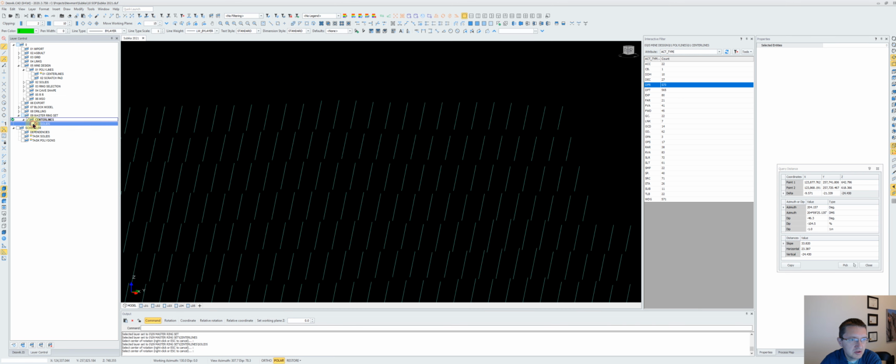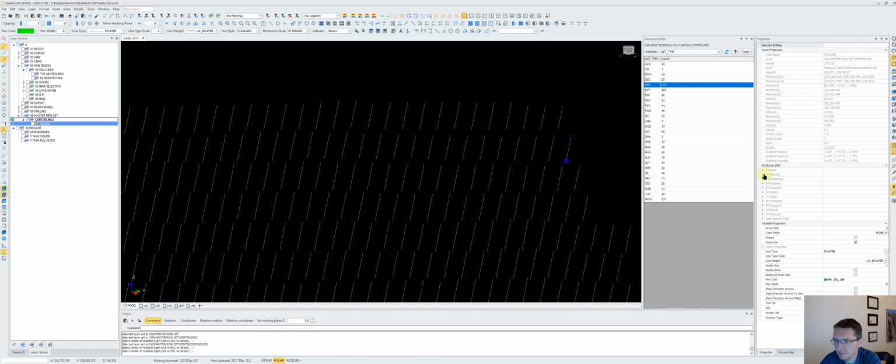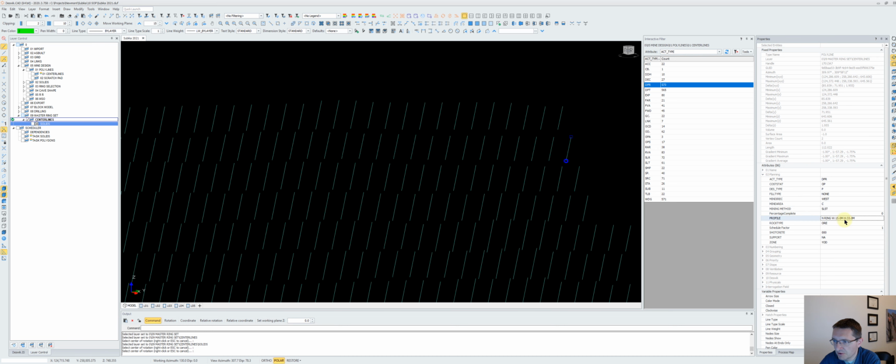So I wanted to show you two things. When you click on one of these center lines, you come into the attributes, you look for profile, right there, N ring width is 15, height is 30. It doesn't really matter what you name it here, just as long as you're consistent and you understand what it is. So this is a ring that's going to be 15 meters wide, W is for wide, and H is for height, 33 meters. When you click on this one, it's only 18 meters tall.